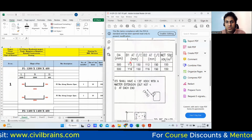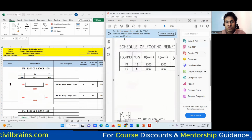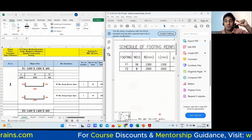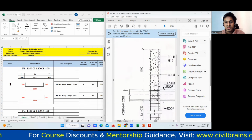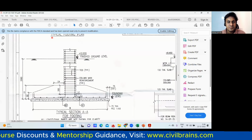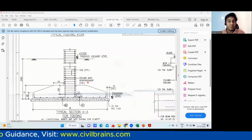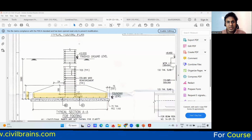What is the depth of the footing? Okay, so in the depth, it would normally be your overall depth, but not in the case of this footing. You're supposed to take this depth. Yeah, you may have a doubt. See, when you're doing this slope footing BBS, your D will be only up to this depth, because your L will go only up to here. So you have to consider D2, not D1. D1 is the overall depth, that is not required. Your L shape will be bent only up to here. So take the D2 dimension.